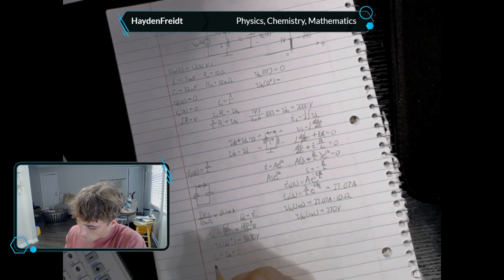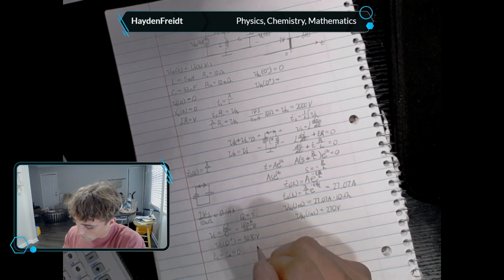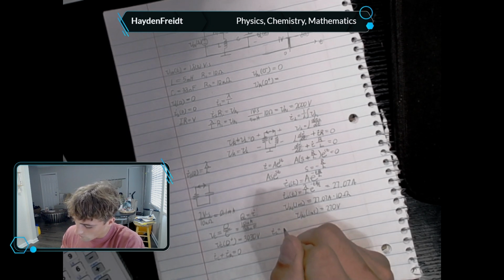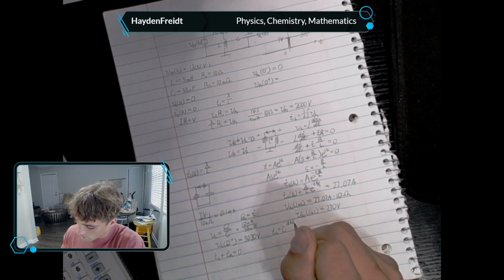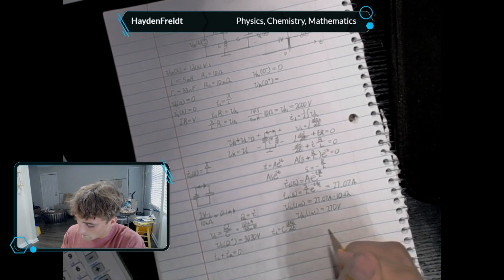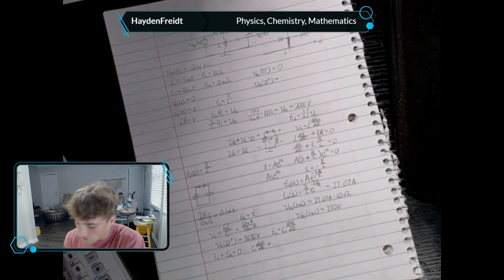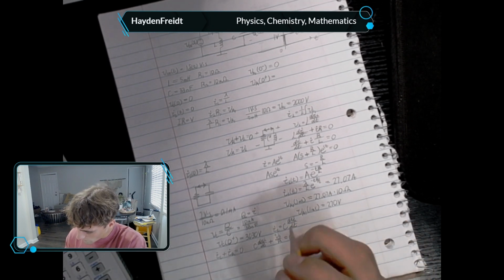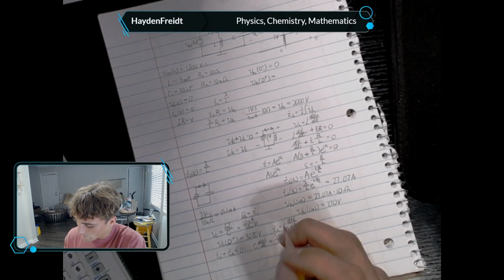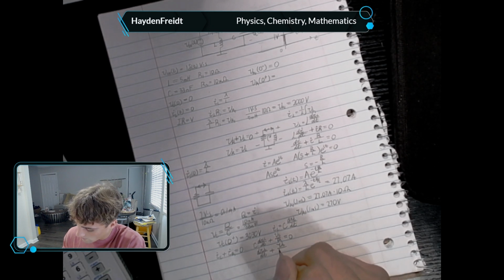Now we plug in our constitutive law for IC equals C times the derivative of the voltage VC with respect to time. We define the current through the resistor by its voltage and resistance, equals 0. Again, we want to get the derivative by itself, so divide by RC.